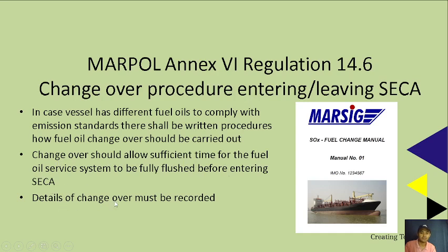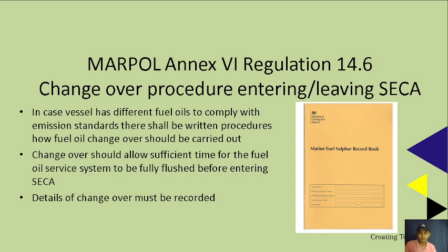The details of changeover must be recorded. Nowadays we have automatic changeover valves that assist the engineers in changeover procedures. These details shall be recorded in the Marine Fuel Sulfur Record Book.